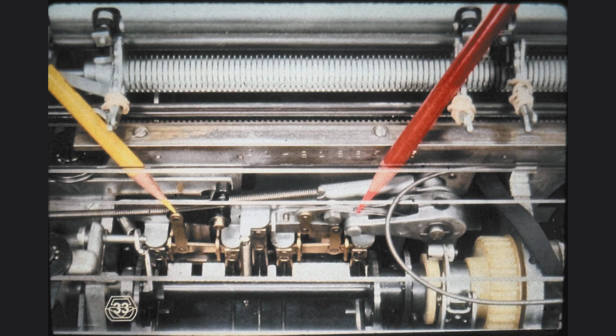The tilt mechanism, or tilt differential, is capable of turning the element in a vertical plane by increments that vary from 0 to 3. With this tilt mechanism, we can select any of the belts around the type element. The rotate differential is capable of turning the element within any of the tilt planes up to 5 rotate increments in the counterclockwise, or positive, direction, and up to 5 rotate increments in the negative, or clockwise, direction.